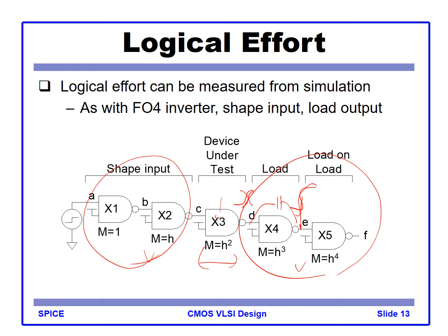This is very similar to analog circuit design. For example, when you design an amplifier, even in analog, most students assume an ideal voltage source going into the amplifier, and no load specified at the output. This cannot properly simulate the amplifier characteristics.